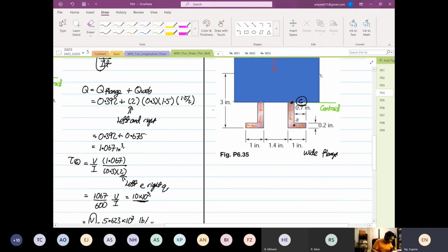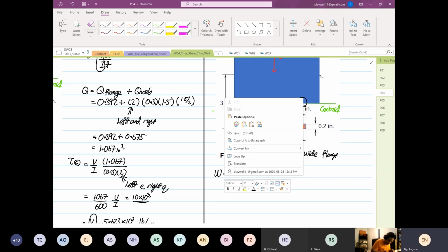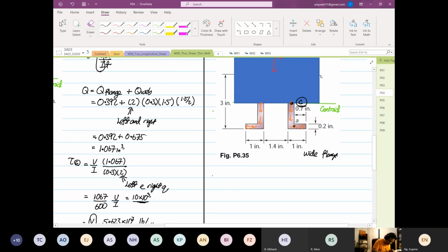And we know when we do our analysis from the bottom, it's no more a box beam. What we have now is a wide flange, so we carry on with a wide flange. Okay, this is a wide flange beam section now. And because the shear flow, the Q on the left did not originate from the right, they're not shared. So that's where now it's only Q.